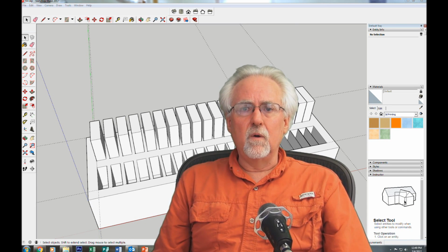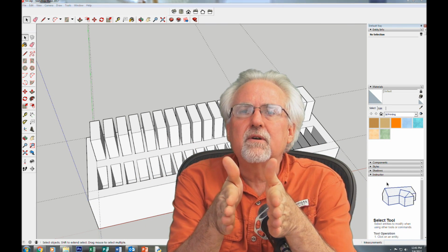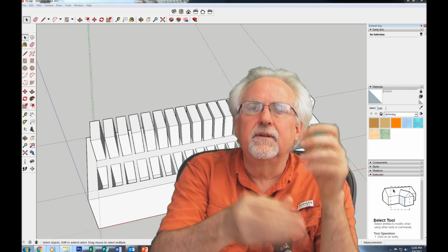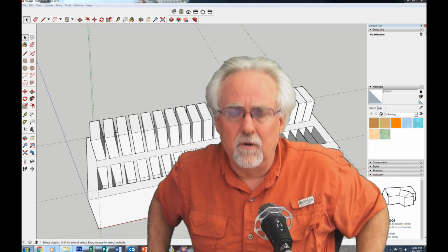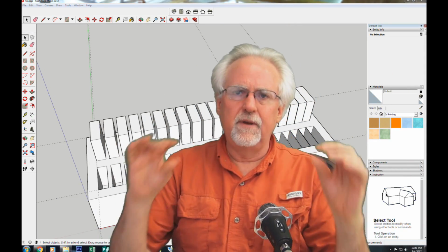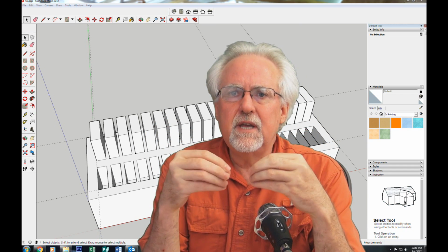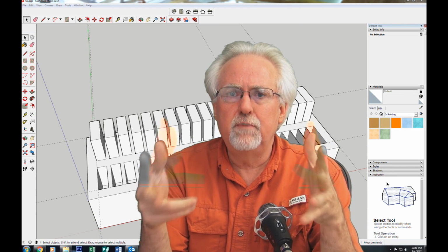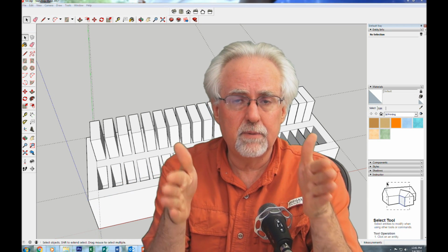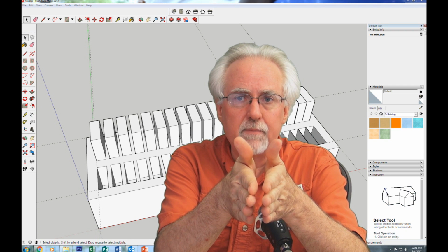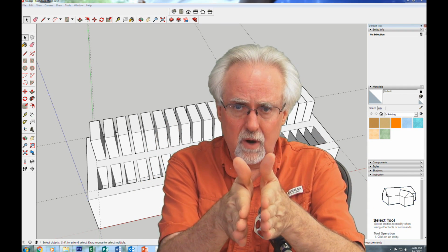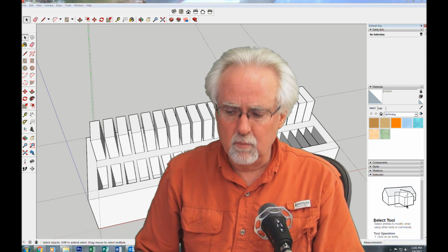Same thing, think of holes. If you put 2 holes, how closely can you put 2 holes together before you lose that little divider and you just end up with 1 big hole? So there's a lot of complex things that you could think of with various design rules, but for the sake of this introduction, let's just think of 2 basic things. With your 3D printer, which might very well be different than my 3D printer, how close can you print 2 objects before they become 1 object, and how close can you print 2 holes to each other before they have become 1 hole?